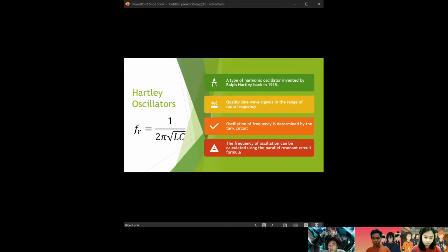Oscillators generate a continuous periodic waveform at a precise frequency by converting a DC input into an AC output. This waveform varies in wave shapes and frequencies. A basic LC oscillator circuit is a type of oscillator where an inductor-capacitor tank circuit is used for giving the required positive feedback for sustaining the oscillations. But these circuits have no means of controlling the amplitude of the oscillations and also have a difficult time tuning the oscillator to the required frequency.